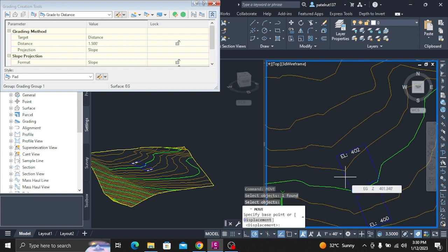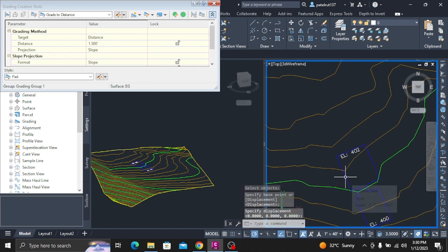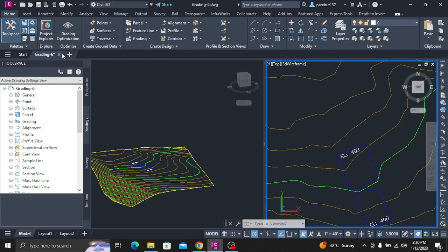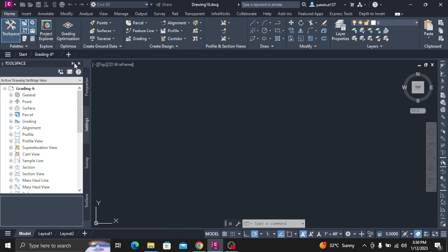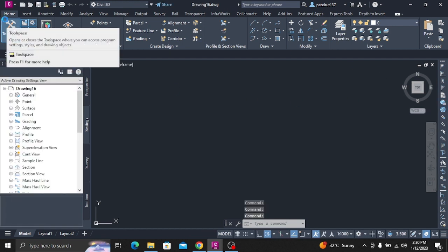Notice that the icon is displayed in the first row. This icon indicates that the building pad feature line also has a PI at this point. When two feature lines cross at a common vertex, both vertices must share the same elevation value. The elevation for both feature lines at this point is determined by whichever feature line was most recently edited. In the following illustration, the common vertex is in circle A. In the Grading Elevation Editor, click on Select All Rows.